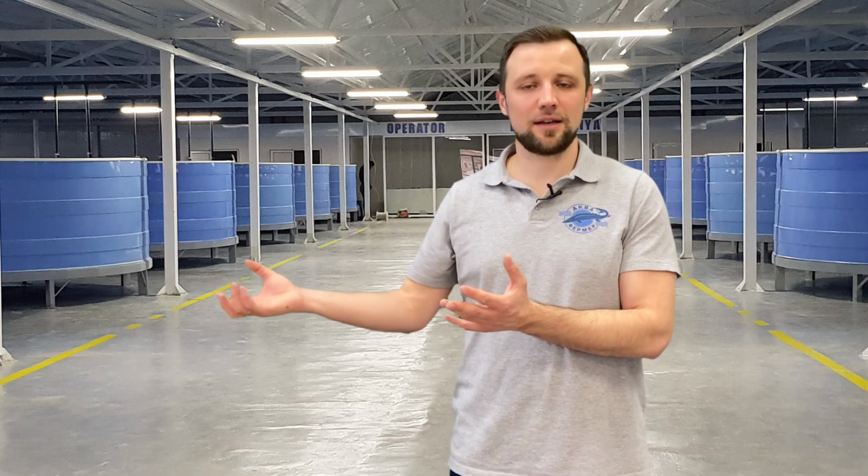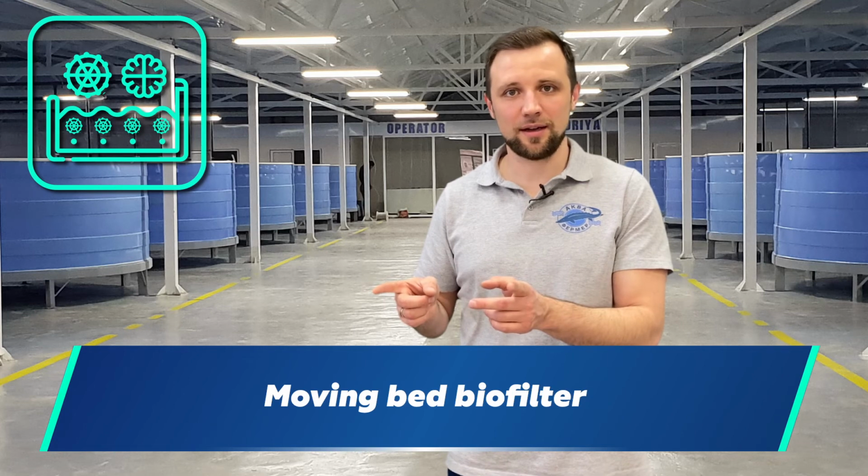What equipment do I recommend? We won't dwell on the tanks, so let's move further to water treatment units. Drum filter, moving bed biofilter. I personally prefer a moving bed biofilter because it's a good and stable technology. It's not very large, quite compact, and in general it has many significant advantages. And also it provides additional water degassing.